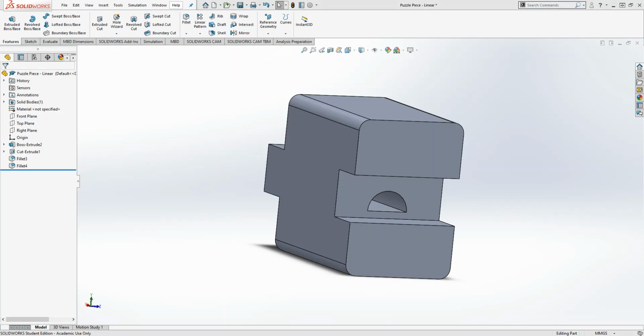Right now it's only going 20 millimeters, so if I wanted to, I could make it 40 millimeters, or just 40 mm, or just 40 would work too. Now it's going to cut all of the material outside of that yellow volume. It's a little kind of overkill. I mean, you have a lot of it out there, but if you just wanted to clear out all the material to that surface, it would definitely work.